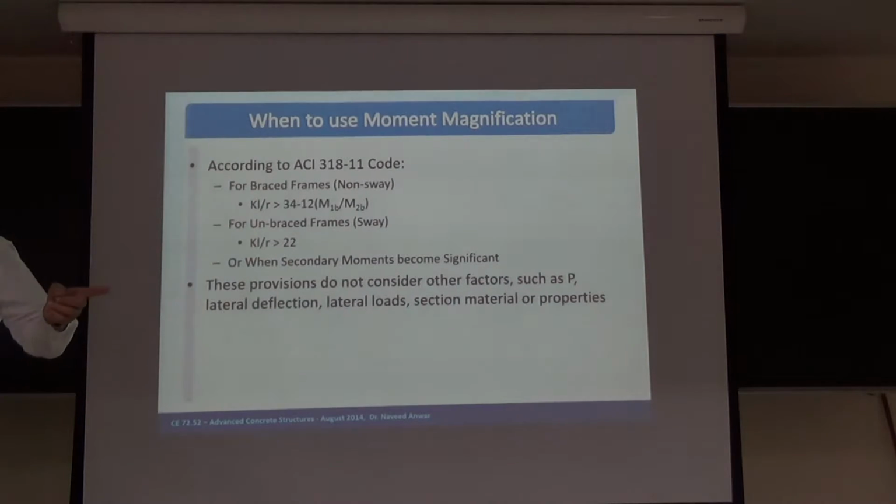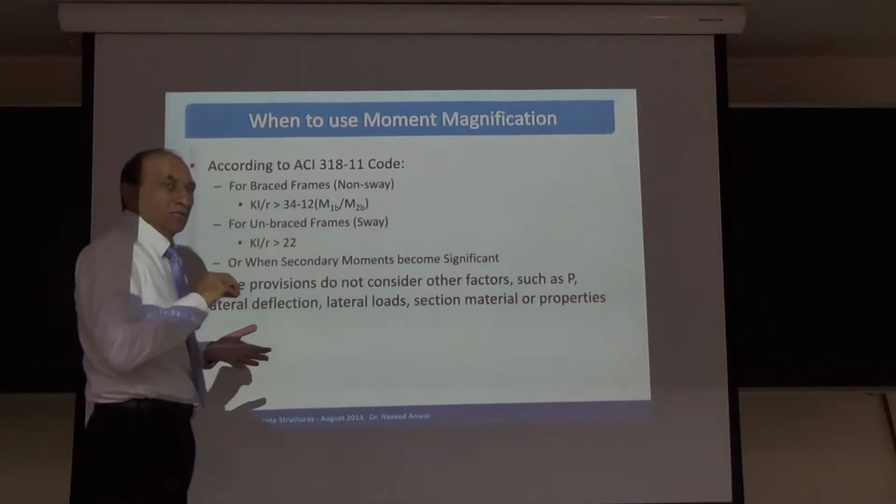Same span, short building, the beam will be the same, 0.8 meter, 0.7 meter, and the column will be now only 0.3 meter. So now the column will become weak because the span is the same, but the column size has become smaller because the load is small. So everything is going against the small buildings.